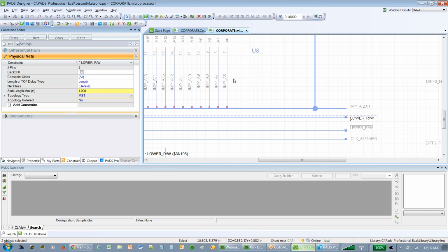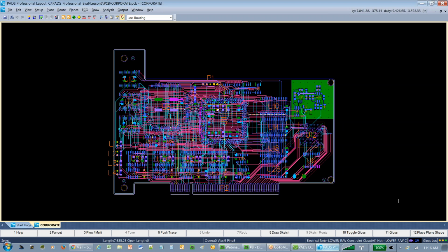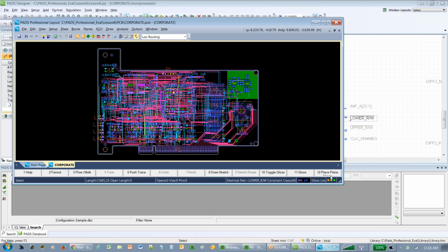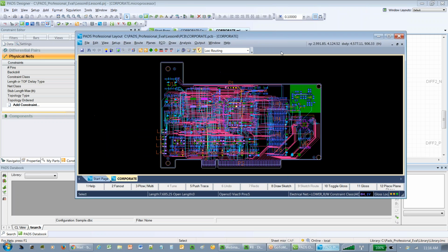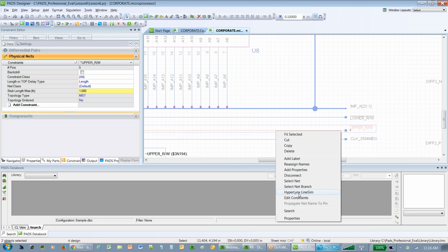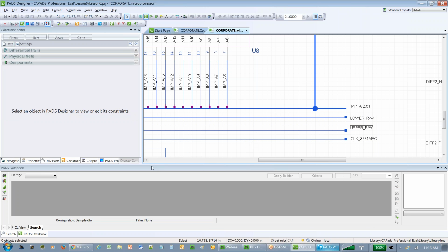And if I'm making updates to a design that's already been started, if I do an update to the constraints here, the PCB designer will be notified again via the little indication lights down in the lower right-hand corner of their window. And they can simply hold their cursor over it, see that there are updates, and they can double-click on that, and it will automatically launch the update process and update their design. So again, making it very quick and easy. Okay, same capability of going to hyperlinks as well.